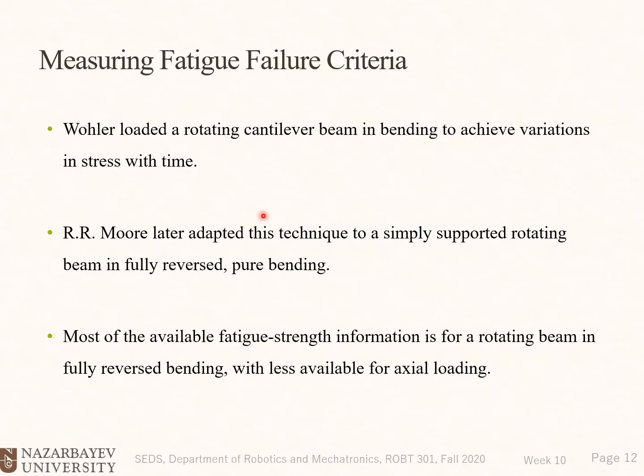Measuring fatigue failure criteria. So before developing any theories, we need to study the experimental data, what people have done empirically in the past to show the fatigue failure theory. Wöhler loaded a rotating cantilever beam in bending to achieve variation in stress with time.